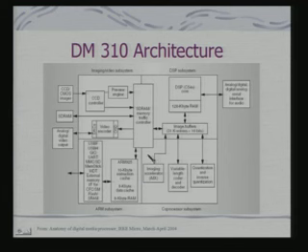The basic difference is OMAP is targeted for communication as well as this kind of media processing applications. This is more targeted towards media processing. So, you have got actually a CCD controller kind of block incorporated into the SoC and coprocessors for each and every task related to media processing. And we can see now how a complete embedded system can be built around it.